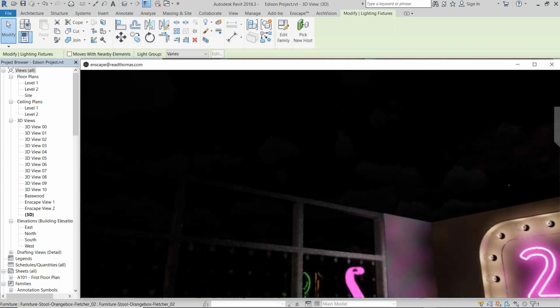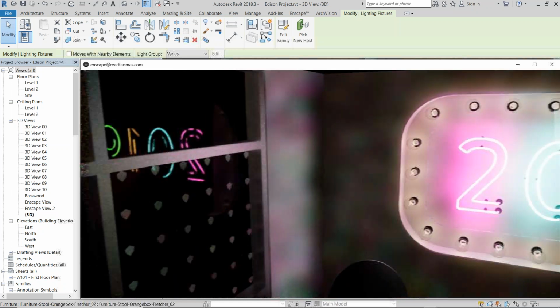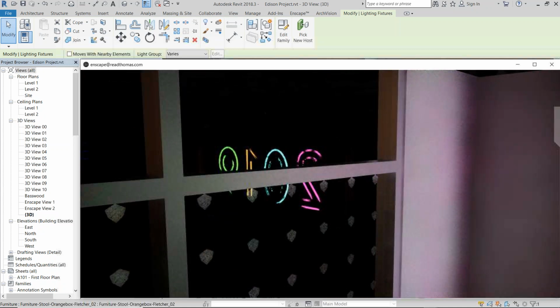Now let's talk about materials. Okay, Revit's almost 20 years old. And when Revit started, think about 20 years ago, people weren't even used to designing buildings in 3D, much less rendering. So you needed a really easy to use way for people to render. And that easy to use way is called procedural materials. They're hardwired for certain kinds of behavior.